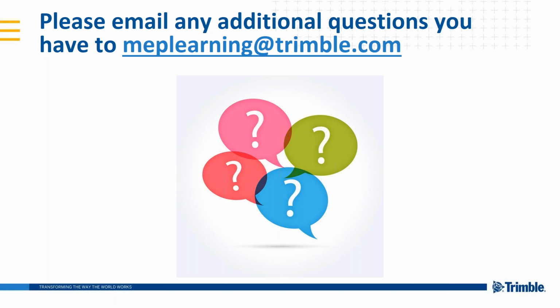Any categories that you might have that aren't in there, you can pull them in at any time and bring them into your database, or bring them into your takeoff on the fly if you needed something. If it's not in your database and you need it just for this particular job, you don't want it in your database, you can do it right in your specials and bring it in there, and then you just have it for that job.